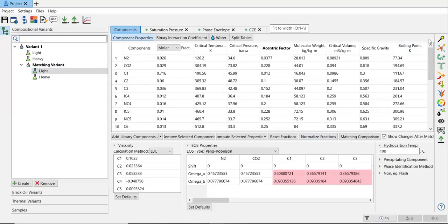The model needs to calculate the molar flow rate and the mass flow rate for each component, and it will make the calculation time for my simulation very, very long. So I need to reduce the number of components by doing lumping. Okay, so I will add many components to form a single new heavier component.